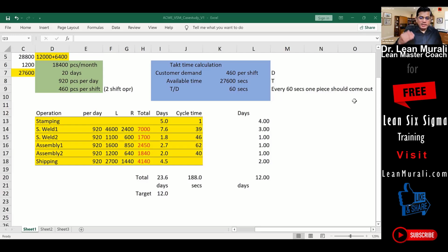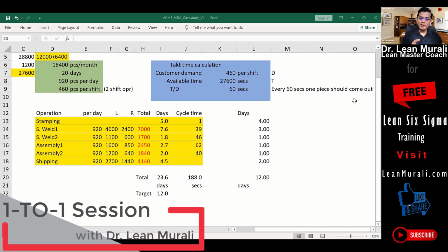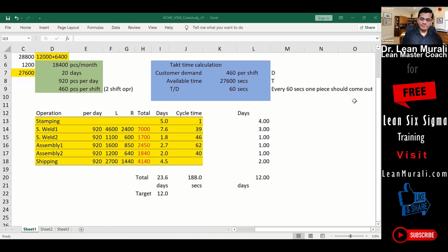I will add something to this because Maninder prompted: it depends upon the cost of inventory versus the profit. And the answer is right thinking. Before the bottleneck, you can keep maximum inventory possible. Inventory before the bottleneck is okay. The reason is, even for a second, the bottleneck should not stop because there is no material. But make sure whatever inventory we keep before the bottleneck is 100% quality verified, because we don't want any quality issues to go to the bottleneck and spoil and waste our time.